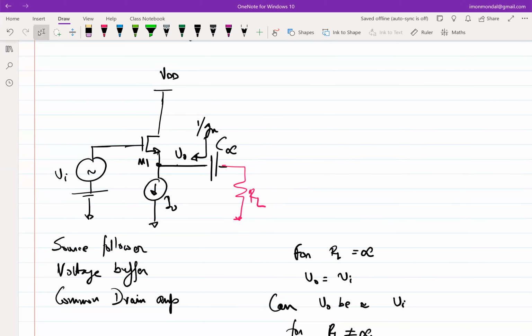So let's start with the left-hand side. Incremental VI is shorted. Biasing is shorted. Then you go to the transistor. The transistor has 3 terminals: gate, source, drain. Even before applying anything, you know this is the incremental model of the transistor: this is source, this is gate, this is drain. This incremental model doesn't change just because you have put it in a circuit. Now, what is connected to the drain? In this case, the drain is incrementally grounded because it's VDD, so this goes short.